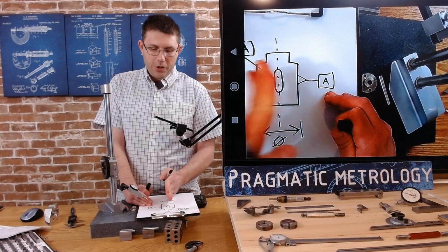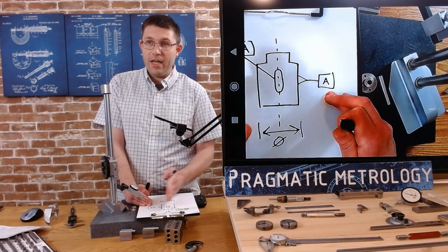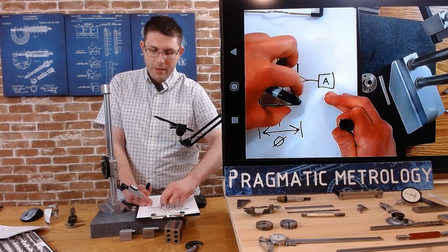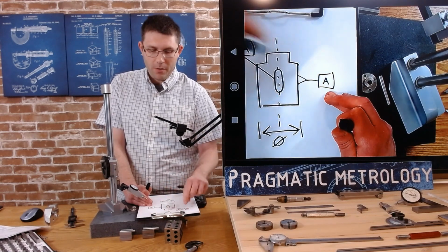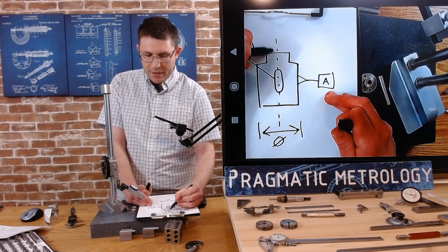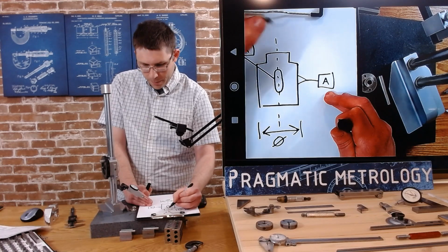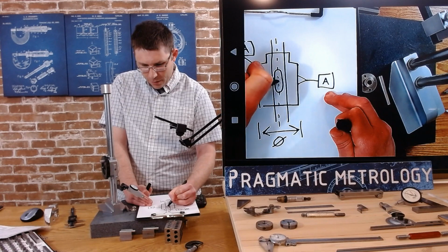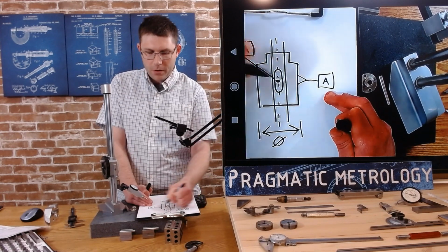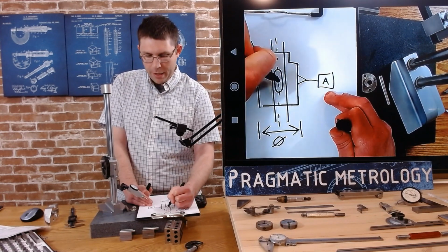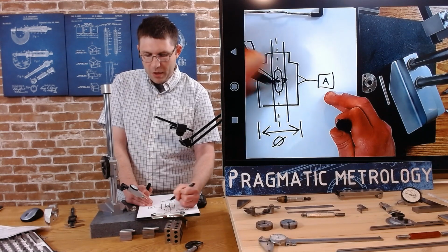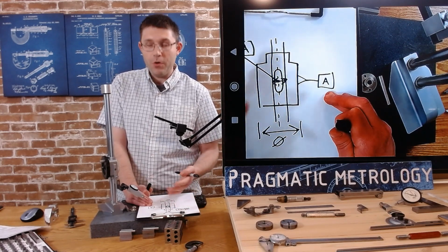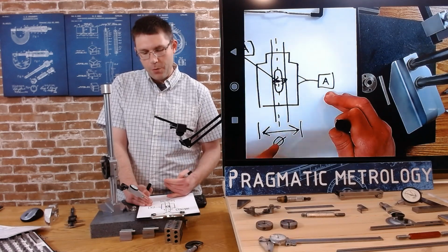This is going to control the side-to-side motion as well as the twist, because it could be a little bit twisted and still be within tolerance. Basically, you're going to end up with a zone for that center point of the slot to move left and right. You could control that with a plus minus, but this would also work. I've seen it both ways.